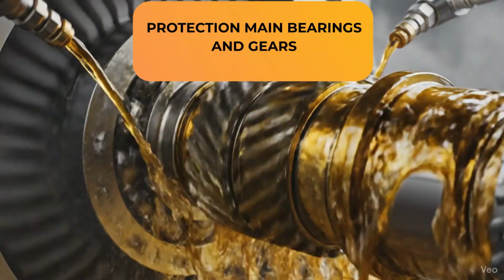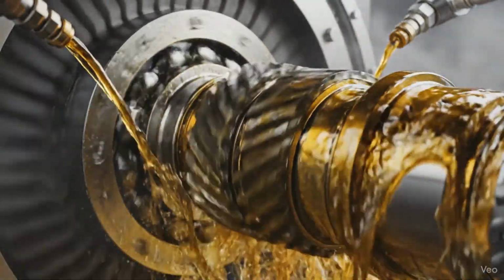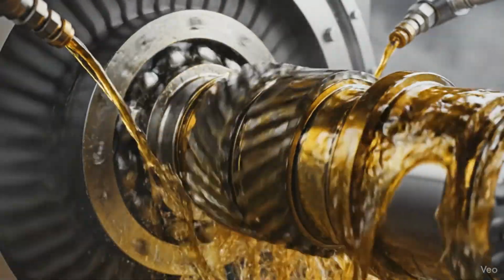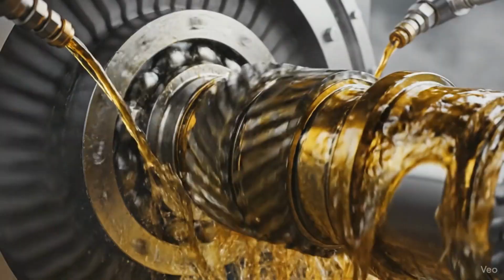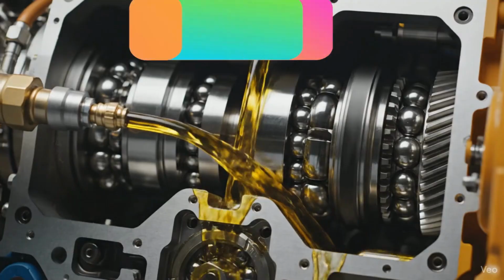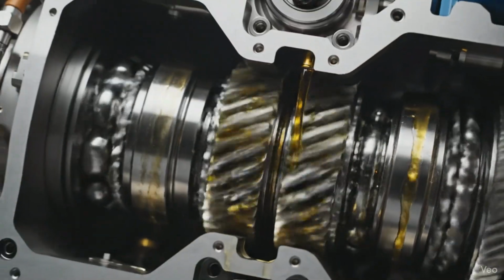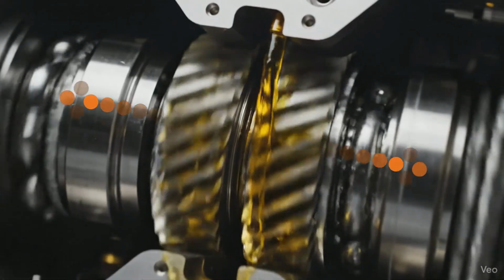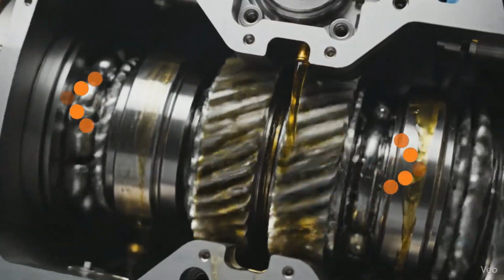Protection of main bearings and gears. In gas turbines, the turbine shaft, compressor, and other rotating components operate at extremely high rotational speeds. Friction occurring within the bearings of these components can lead to system failure in a short period. Lubricating oil protects these bearings. Heat transfer. Secondary cooling is critical to prevent damage to metal components caused by the high temperatures generated, particularly in the turbine section. The oil absorbs heat from these regions and transfers it to the oil tanks or heat exchangers.